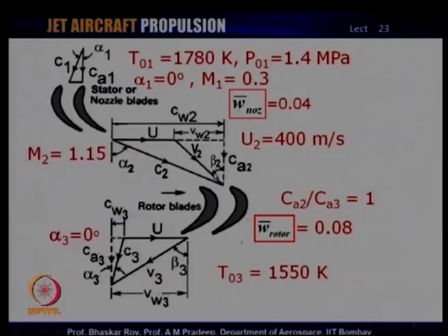And as I have mentioned earlier, this is done deliberately, that most of the modern turbines today still admit flow into the rotor which is subsonic. It is indeed possible to admit flow into the rotor which is supersonic. That means, you can indeed have supersonic rotors, but normally in aircraft gas turbines even today it is not a done thing. Supersonic rotors have been used in other applications, notably in turbomachinery applications in spacecraft, but they are normally not used in aircraft gas turbines.